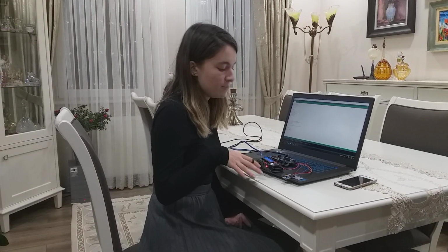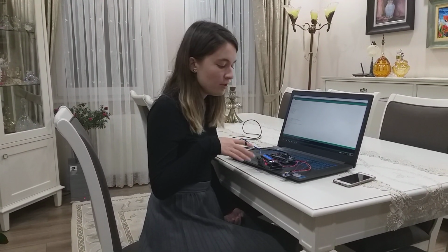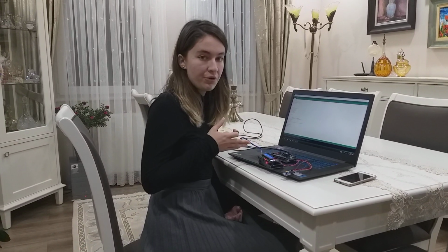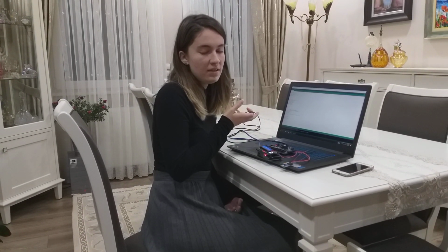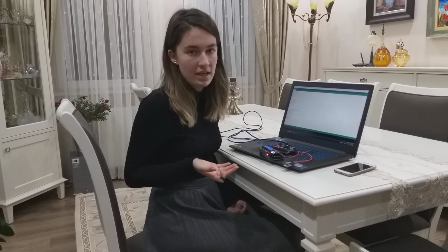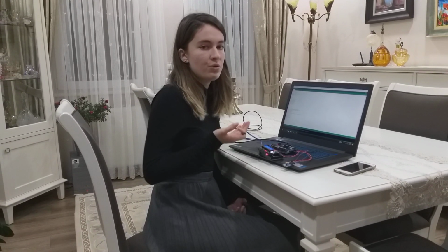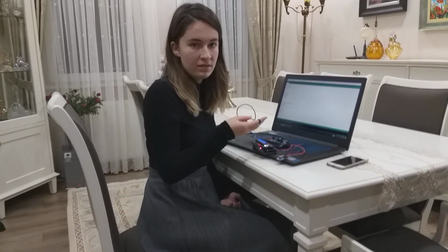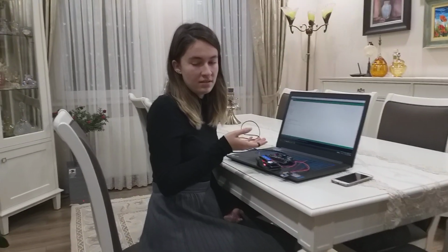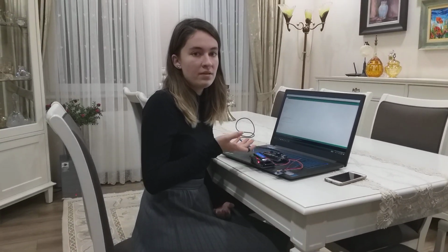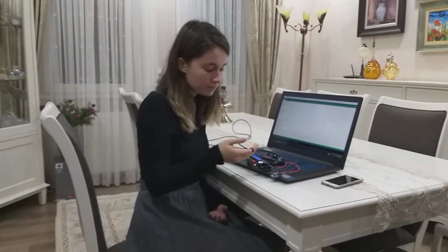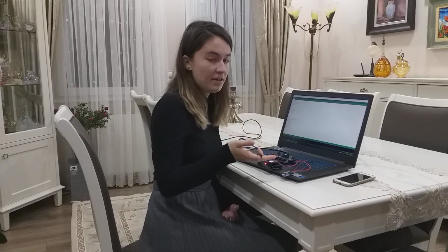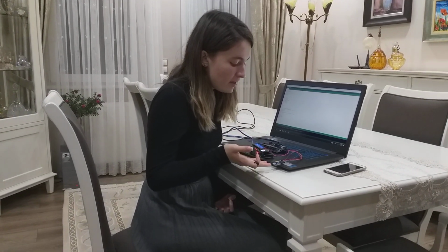Also, just for the PMod Mic 3 module, the communication occurred in 16 bits, by putting the data into a data buffer and then receiving it. My code had 4 states in order to do this. First, enabling the communication between them. Second, loading the data. Third, setting the data, setting the output. And the fourth one, getting ready and enabling the ready signal.